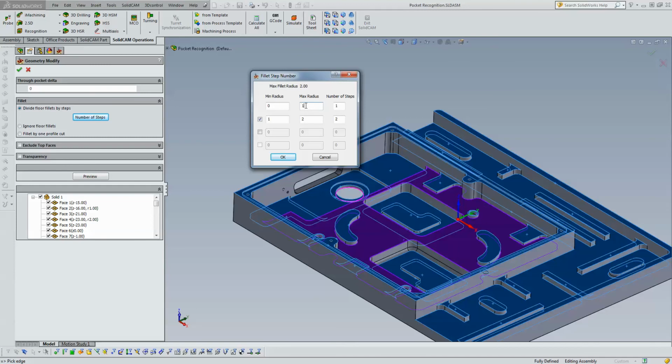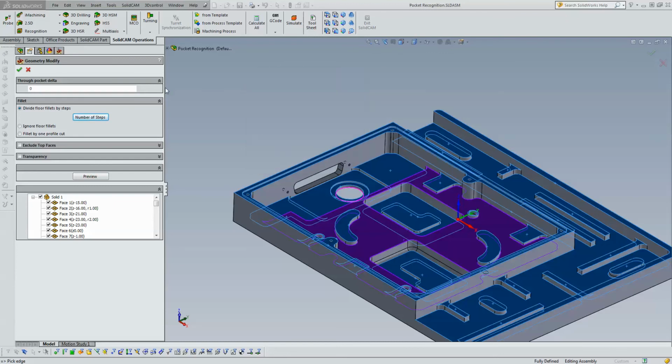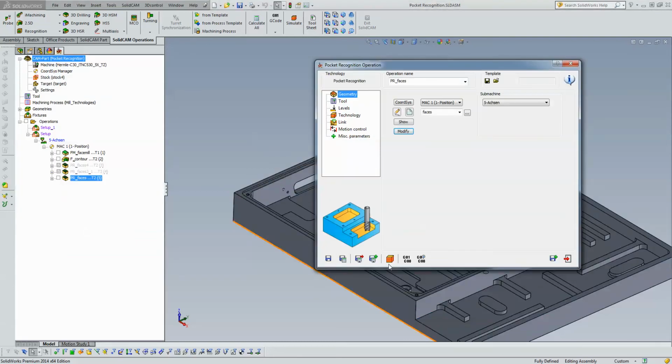Now, I can also change it if I want to, say to 0.75, and note that this line will continue from that point on. I can do whatever I want over here, have it in any way. Let's just leave it at 1 millimeter for now. So anything between 0 and 1, this is the number of steps it's going to do it in. Let's change this actually. I like to do it, say, in 2 steps. And anything between 1 and 2 millimeters, I want to do that, say, in 3 steps. Okay, now that I've accepted it, let's take a look at our simulation.